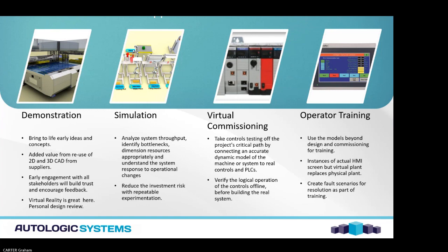We flow from having done our design sign off, and the opportunity is there to move into the world of virtual commissioning. So we're taking our commissioning of our automated plant off the critical path. We connect and communicate into our PLC and our higher level software layers, and those environments think that the digital twin is the real world.